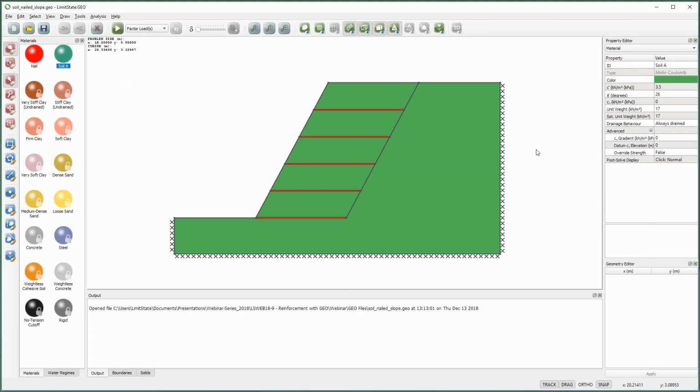And that is essentially captured by these coefficients NQ and NC. So NC captures the component of lateral resistance due to cohesion, and NQ captures the component of lateral resistance due to friction, and will be dependent on the prevailing normal stresses at that particular point.